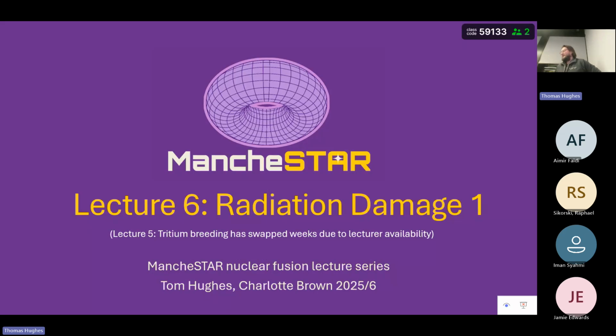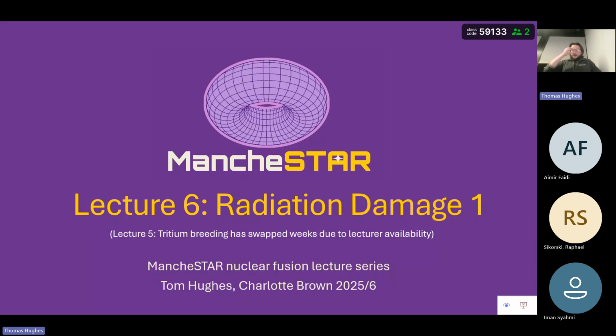Yeah, but what about the durability of the reactor itself? Is it less durable? Well, arguably it's worse in lots of different ways. I don't know if you've ever done any material science or materials for engineering and failure mechanisms. Tokamaks will generally run at high temperature for a long time, so you'll get problems like creep happening. Whereas for this, because it's bursts, you'll have a lot of thermal fatigue. So it'll fail that way because it's going hot to cold, hot to cold, hot to cold. So it's going to damage your material in that way.